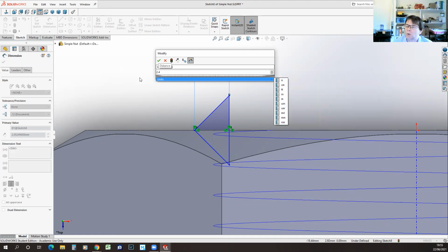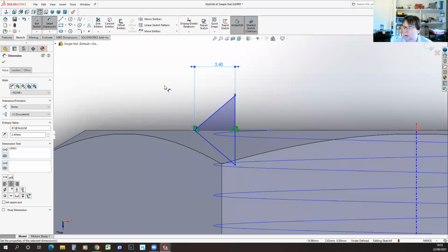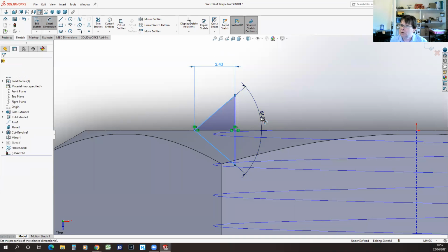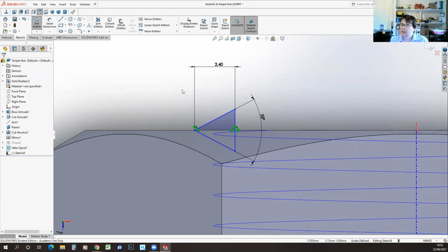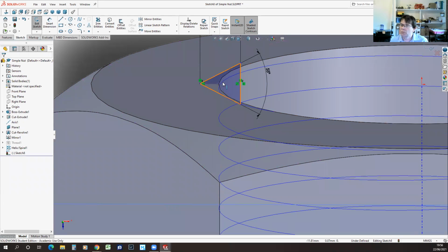Now this is where doing this manually, you've got some additional control. Because I wanted to 3D print this, I think I might have actually made this slightly deeper than it needed to be for a strict kind of thread definition, because when you 3D print, you find there's a little bit of expansion sometimes in the plastic compared to the dimensions you modeled. And I managed to fine tune this so that I could 3D print this, and the thread just worked without needing any finishing. And the other dimension we had there was this angle, which is 55 degrees.